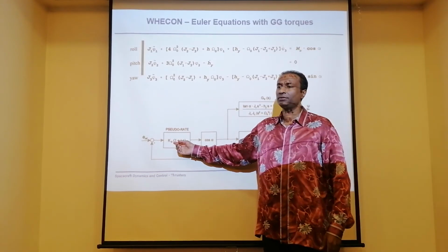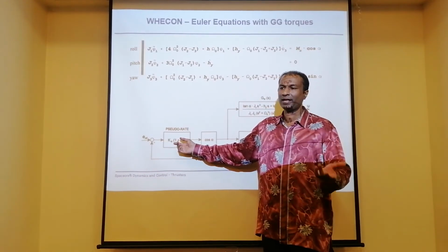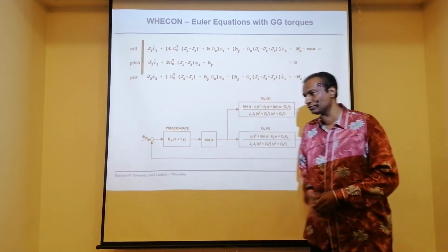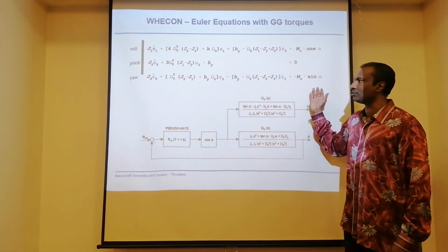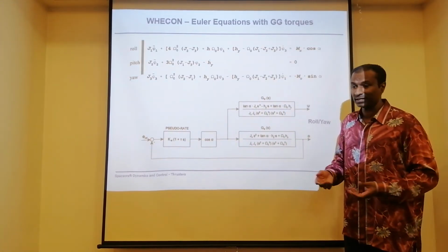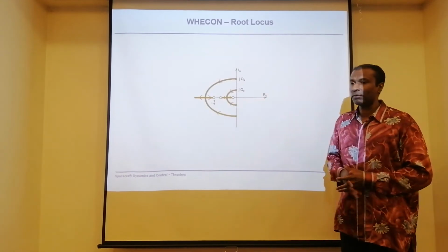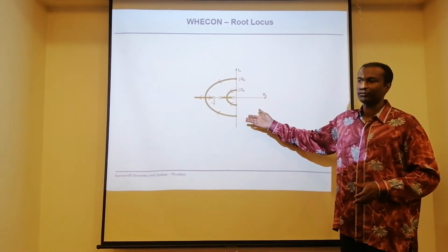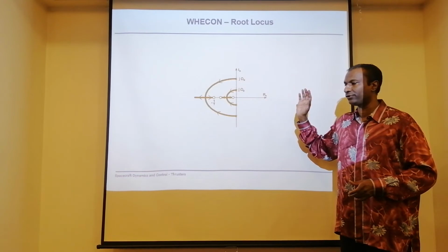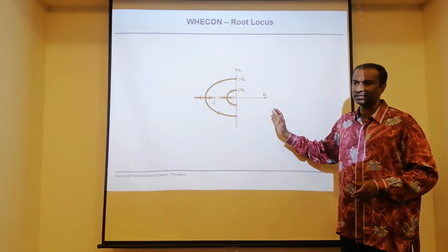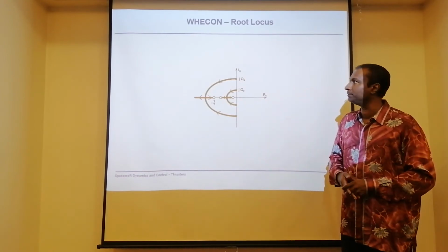You want to look at the gain, that means the proportional gain and the derivative gain. How to do that? To select that, we do a root locus. For example, you can do a root locus or a Bode diagram, in order to find the poles and ensure the system is stable. This is very typical in control systems.